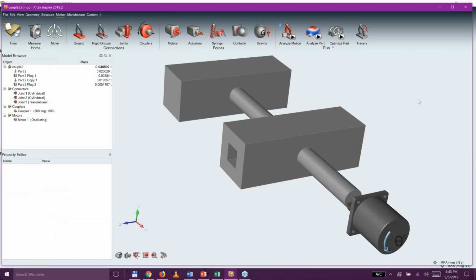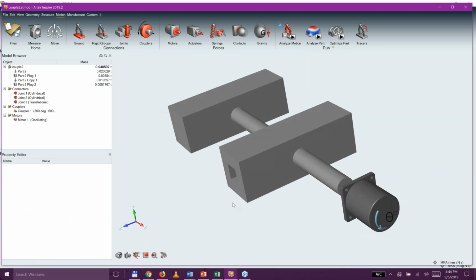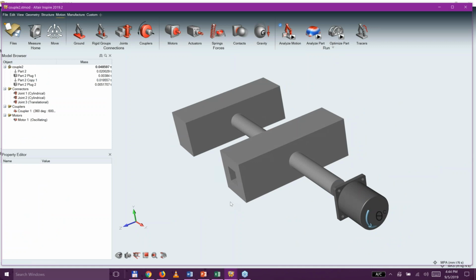Hopefully we all know what a rack and pinion steering system is. You turn your steering wheel, and it takes rotational motion and converts it into linear motion. Now I could simulate that on here. I could create a rod that represents my steering column, connect it to a gear, and create a gear on my axle, what moves the control arms that causes the steering. So I could physically model a rack and pinion system and then define contacts between the gears.